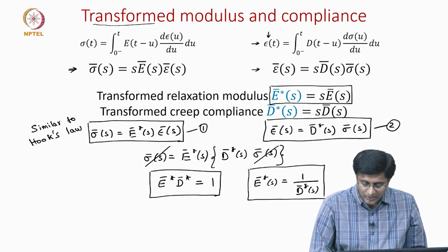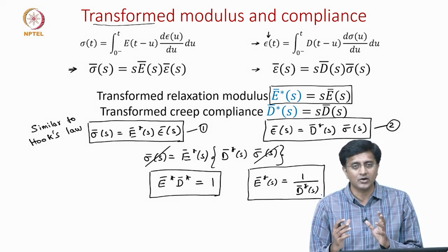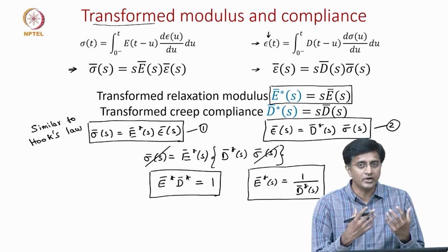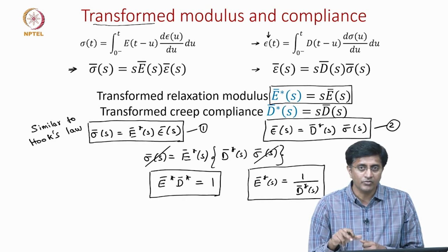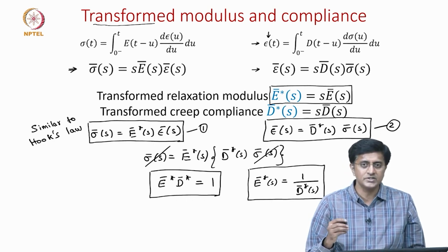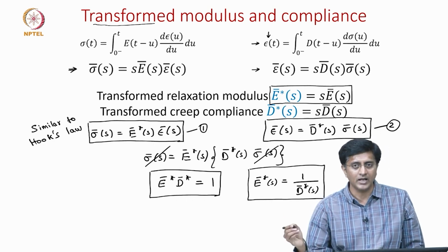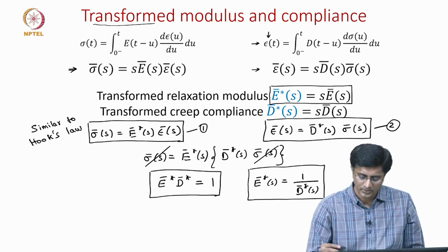So, the reciprocality between the modulus and the compliance which we have seen for an elastic problem, we can see in a viscoelastic problem. The difference is we are seeing it in the Laplace domain, but not in the time domain.